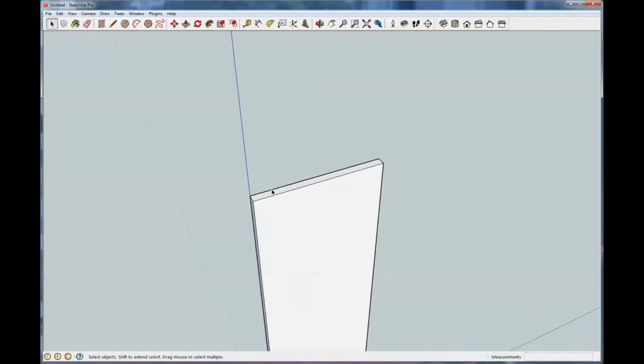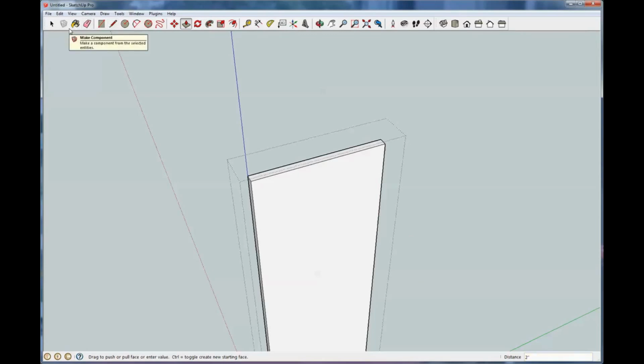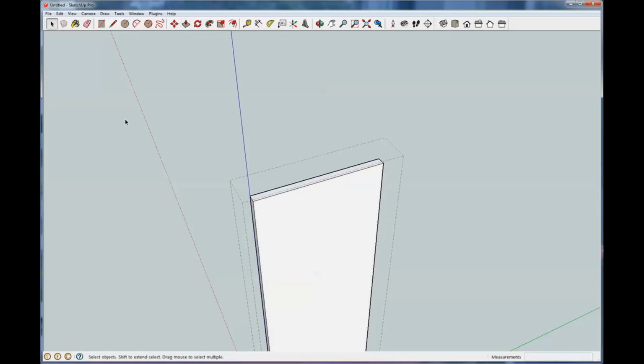By the way, once we go into that edit mode that we talked about by double clicking, we can use that pull on anything. See, I can make it longer. We were 48 inches. If I typed 2 here, pulled it the direction I wanted, we just added 2. We now have a board that's 12 inches deep by 50 inches tall. I'm going to undo that and drop back down to 48.